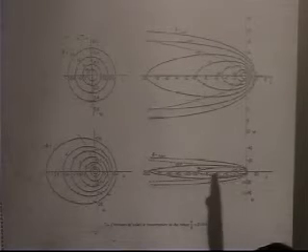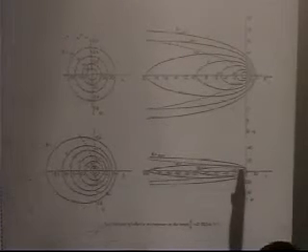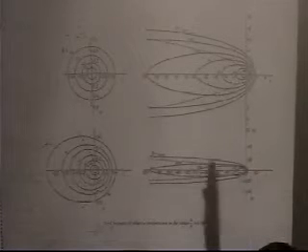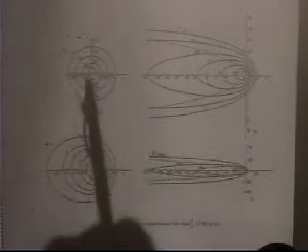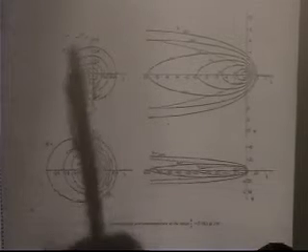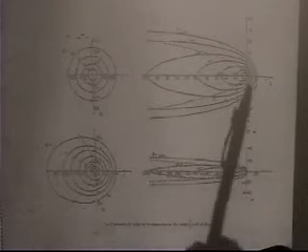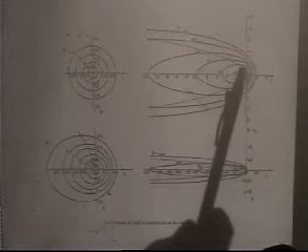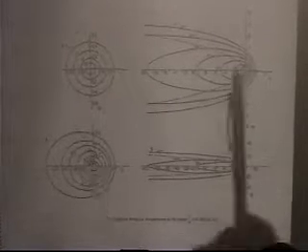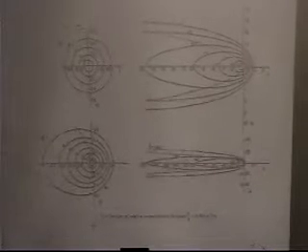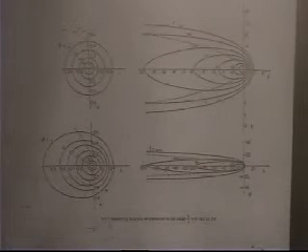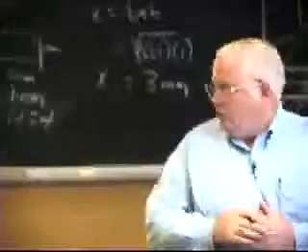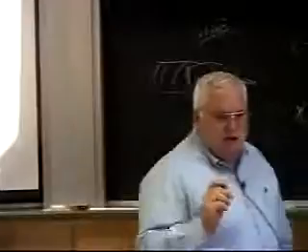And so it turns out that for something like this, a very fast weld, like laser or electron beam, it's the cooling part of the cycle that controls the width of the heat affected zone. On a slow weld, like electroslag or oxyacetylene welds, it's the heating part of the cycle that controls the heat affected zone. When I get in here, I'm getting into a kind of transition ambiguous region, and this is basically arc welding. So in arc welding, I can actually change the size of my heat affected zone by changing the travel speed or the heat source intensity. Either one of those has the potential to change the size of the heat affected zone.